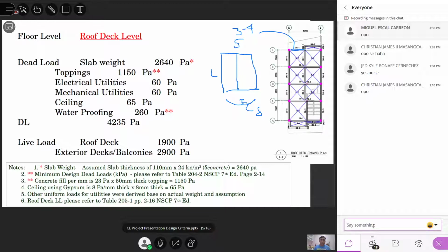Okay? And if your slab is between 3 to 4 meters, and it is residential, usually the maximum will be 110 mm. Okay? So kung mas mabigat yung load yan, let's say school buildings o kaya mga hospitals, usually ang maximum nga mga 125. Pagka dinesign mo yan, lumalabas 125 ang maximum thickness mo. But for residential, kalimitan mga 4 inches lang yan. That will be the minimum. Do not use 3 inches or 75 mm. Okay? So if that is 110 mm, times mo ng 24, that is 2.64 kPa. So wala nang problema. Alam na natin paano nangyari yan.